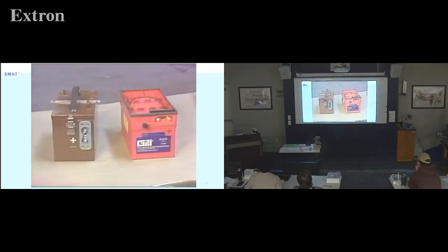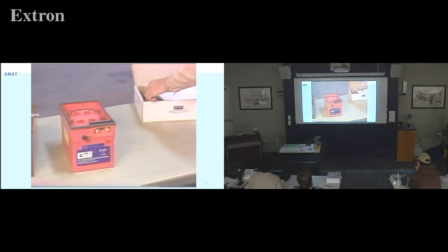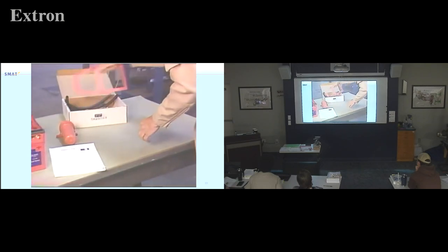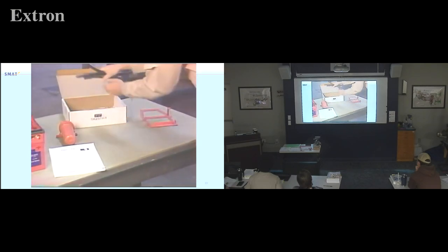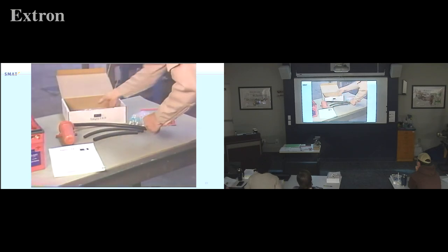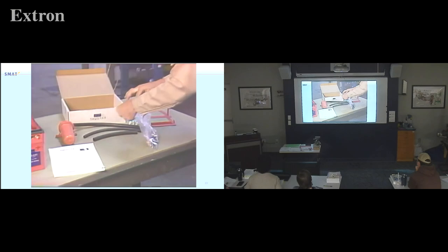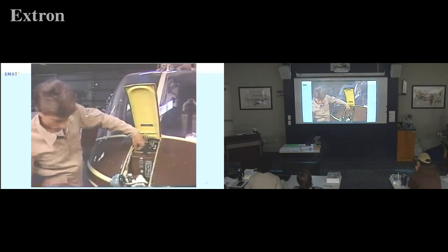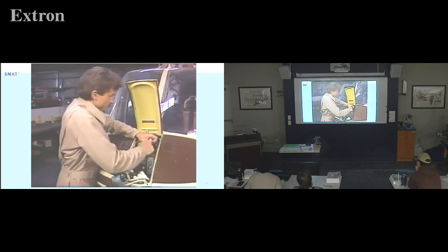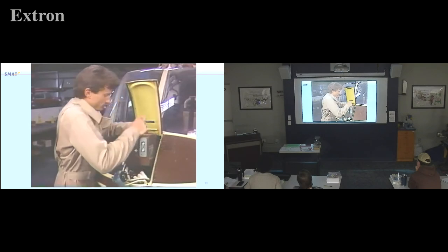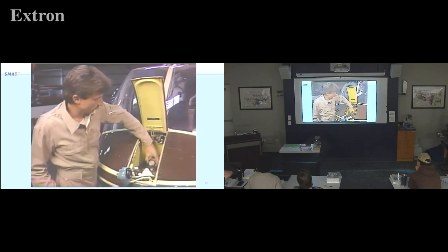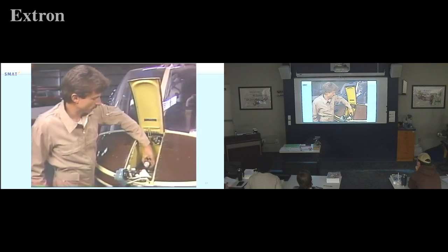Many turbine aircraft have been converted from NiCad to GIL lead-acid batteries. If you are to perform a conversion, ask your GIL distributor for the proper STC, which will include a kit containing the parts and accessories necessary for proper installation. The STC kit includes instructions for deactivating heat sensing or current monitoring equipment required for NiCad batteries. This equipment is not necessary for lead-acid batteries.